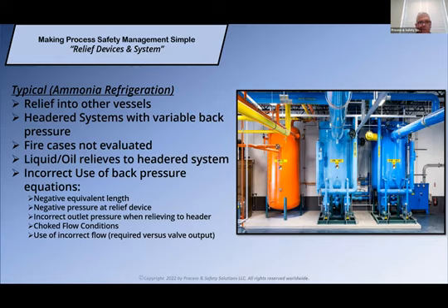Can't have negative pressure drop either. You know, it's going to atmosphere. There has to be some pressure at the valve in order for you to have flow. And flow is not going to go from atmosphere back to the relief valve. So we need to make sure that, again, the results make sense.